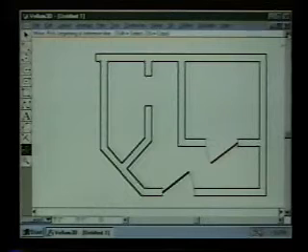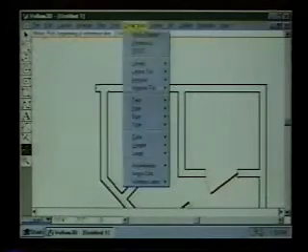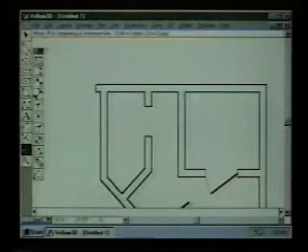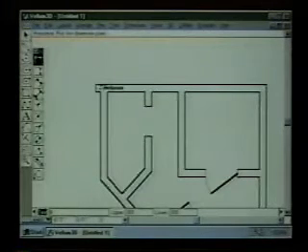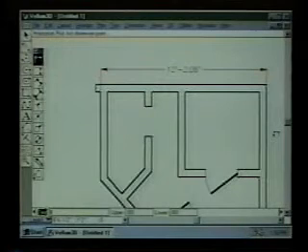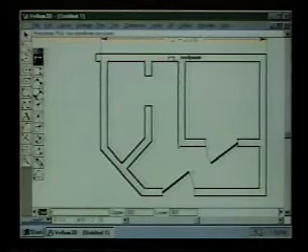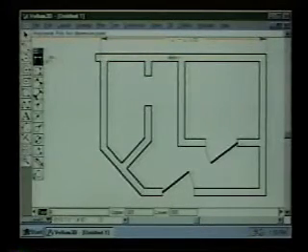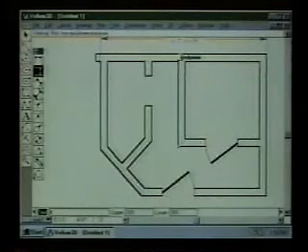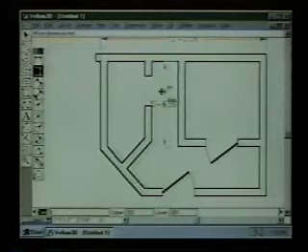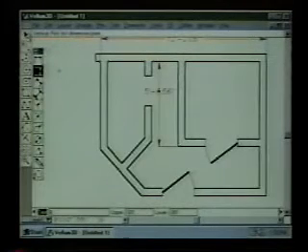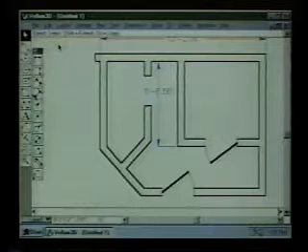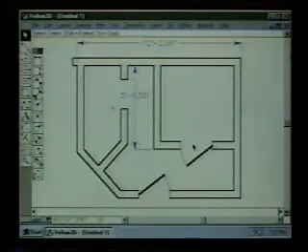And then another common thing to do is to put dimensions on this, so I can bring up my dimension palette, grab my dimension tool, and then I can hook on to an endpoint here and an endpoint here, and this dimension shows up exactly. And then I can come down and say, well, how far is it from here to here? Oh, I need to change tools, of course, so I go here and pick this tool and go for a vertical distance from there to there, and let's slide it up to something like that, and so on. So you can sketch your walls very quickly, and then you can add your dimensions and your door and window symbols and do very quick, very powerful layouts of architectural things in Vellum.